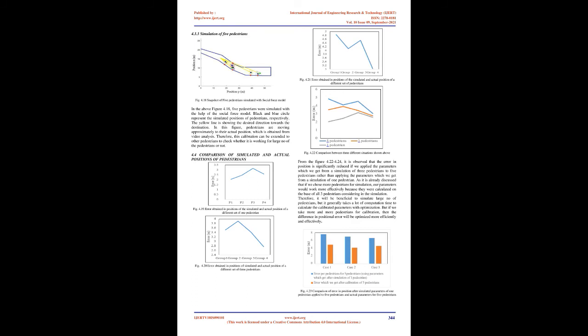From figure 4.14, it can be concluded that initially, the pedestrian flow was very low at the junction as it was crowded, and no pedestrian was allowed to move. But with time, more pedestrians entered the length of road for the ongoing event, and when the pedestrians were allowed to move, more and more pedestrians passed from the observed section of road to their destination, and pedestrian flow started increasing.